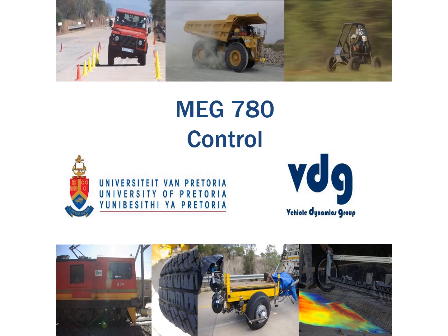So up to now we have built all the building blocks to develop an electrical and mechanical system that can interact with one another. We know how to control the actuators using typical electronic circuits, for example like an H-bridge or MOSFETs, in order to actuate a DC motor, brushless DC motor, whatever it might be. We also have developed the information to sample all the data, making sure we don't have aliasing of the signal, adding some filtering if needs be.